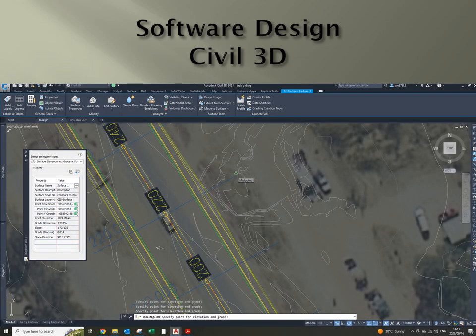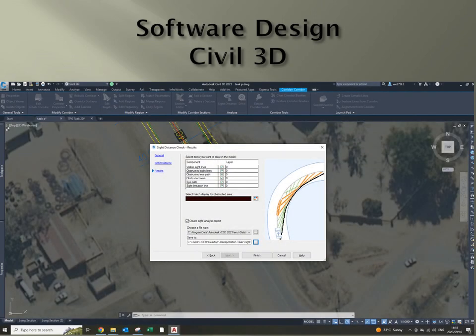Civil 3D is capable of identifying the storm water flow direction on the road. Here you can see the water will flow to the outer edge of the road as designed. And then, just a sight distance check, the full report can be seen in my assignment.